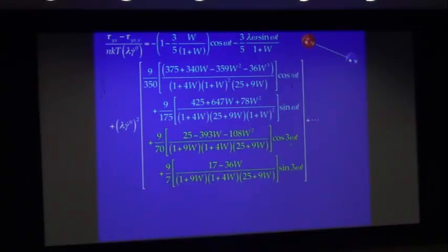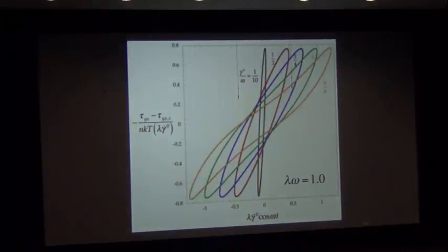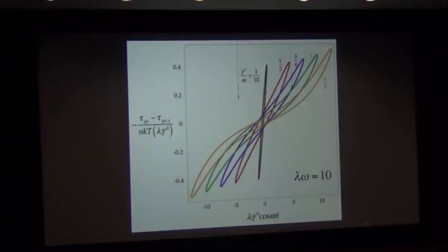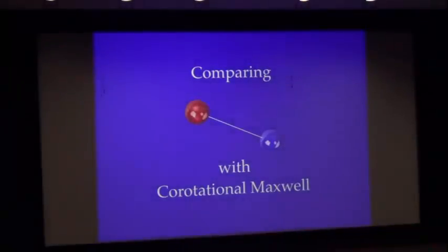The amount of work here was 10 times the amount of work for the continuum theory. I think you can see why we prefer to solve the problem by neglecting the molecules when we can. Of course, if you're a chemical engineer, you really hate to abandon the molecules. That's why you went into chemical engineering, right? And if we look at this carefully, we can see the distortions of the stress response from the shape of an ellipse, which we would obtain for the linear case. I think you've seen that the math comes out in parallel for the molecular theory and the continuum theory.